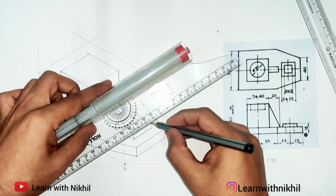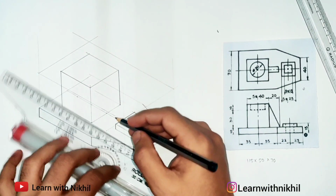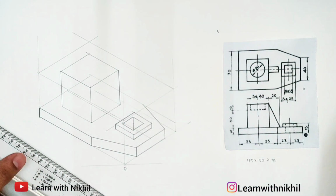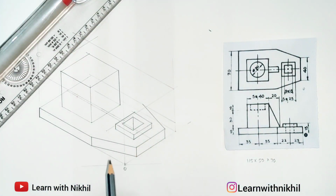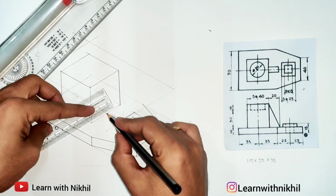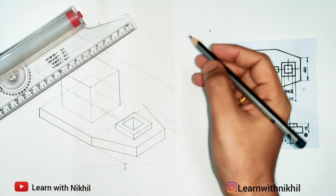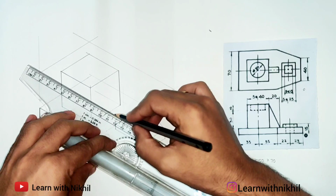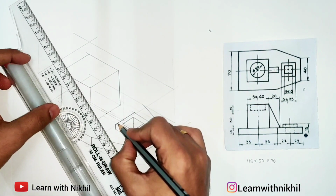So look how I am drawing. I have marked a distance of 40. So it exactly touches here. So the slant line is hidden from this angle, its bottom part. So it is hidden. As the thickness is 10 millimeter, from the center 5 millimeter on both the sides, it is not given in the question, so we have assumed it. So drawing light lines till the distance of 20 millimeter.